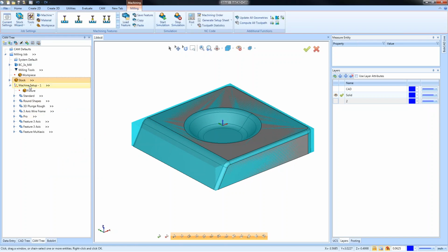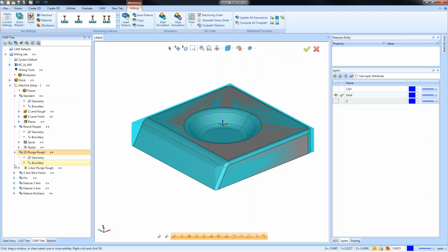One of the things you'll notice when running the job template is that it picks up the stock size that I used when I saved the template. Mark says, let's build the template. I agree, I'll go into that. It loads the stock size, it will also load the zero, and it has all these machining strategies already in here.